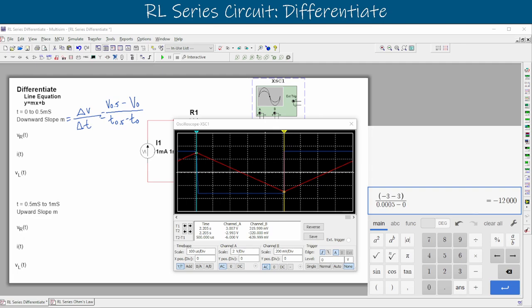We're going to multiply it by this magnitude value of negative 1200. So we'll set that out here. We'll say equals negative 1200. And that's our slope, so we can plug that into our VR. We can say that the voltage drop across our resistor is equal to our m, negative 1200, times an unknown time value for our x, plus our starting voltage. And we know that that happened at this top interval here, that's T1. And we see T1's starting voltage is 3 volts. So we'll plug that in, 3. And you can keep the voltage on there if you want to keep that in mind, because you might be able to spot some of the Ohm's law as you work through this.